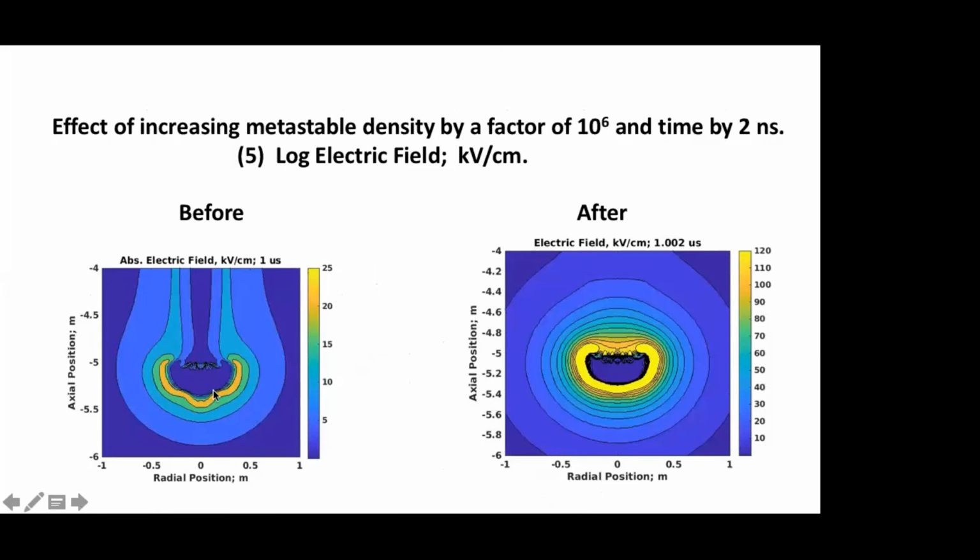Well, because this is really conducting, it's like attaching a conducting wire to a high voltage source. So this connection with the cloud raises the potential to that approximating the cloud. But at the edge of this conductor, the field is increased enormously, from 25 kV per centimetre to over 100 kV per centimetre.